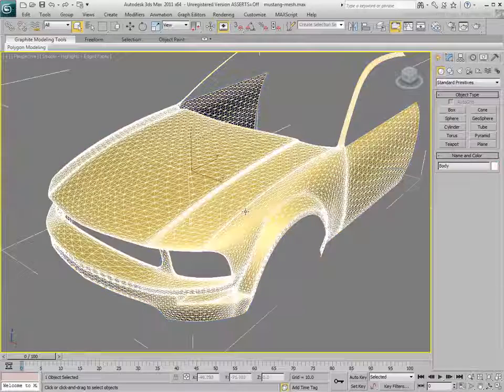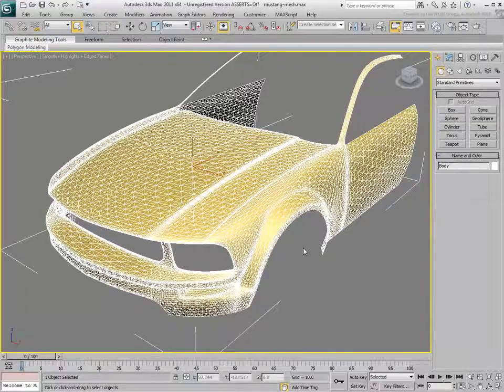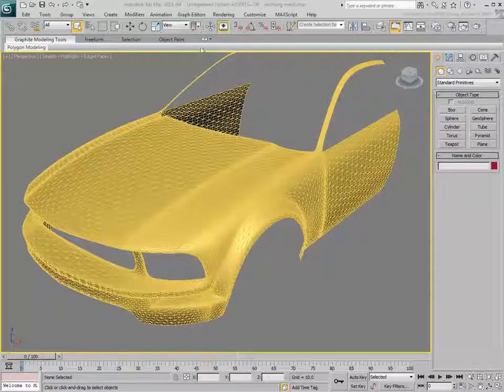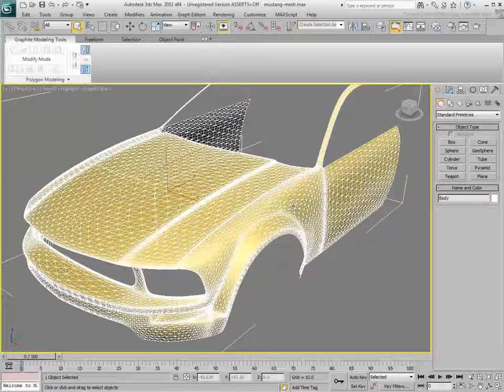In this example, we have a partially built car body and the model shows a large number of triangular faces. This may be because the model comes from a different application, a 3D scanning device, or was simply modeled this way. If you are more partial to models made of quad polygons, then the Topology Freeform feature is for you. You can use it to rebuild the model using the following workflow.